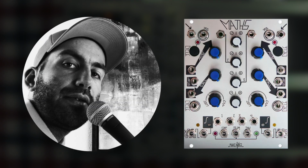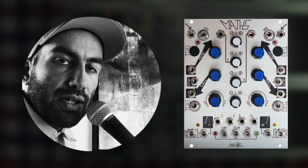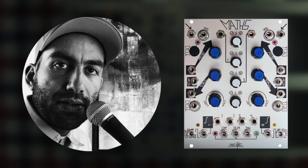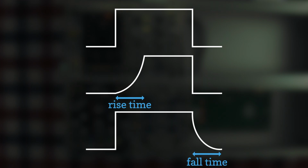The other little piece of theory, which will make the module easier to understand, is this concept of rise and fall time. This allows you to basically lag process a signal. The rise time determines how long it takes for a signal to go from one voltage to another, and fall time determines the same thing but in the opposite direction. Rise time is from low voltage to high, fall time is from high voltage to low.